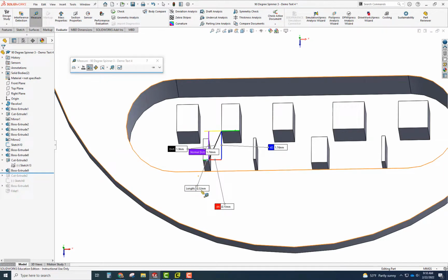In fact, the nozzle size for the printer is 0.5. So if you're trying to print less than 0.5 millimeters, which is the minimum size, obviously it can't do that, so it's just not going to print it. This is smaller than that. So that's why these three are not printing. They're just too narrow. The nozzle literally cannot print those.